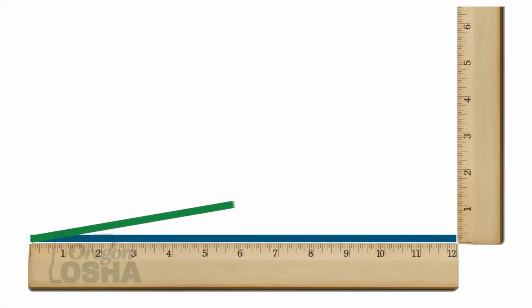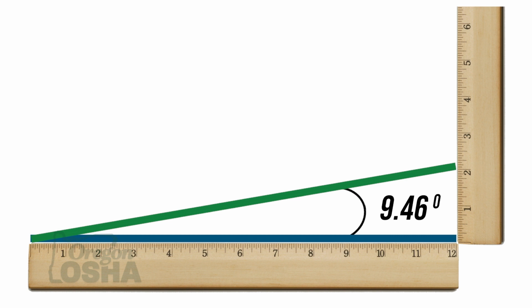So on a warning line, you are restricted to the slope of the roof. You can only use a warning line up to a 2-12 pitch. Anything below that you're fine, but anything above a 2-12 pitch, you have to go to the standard fall protection scenarios.